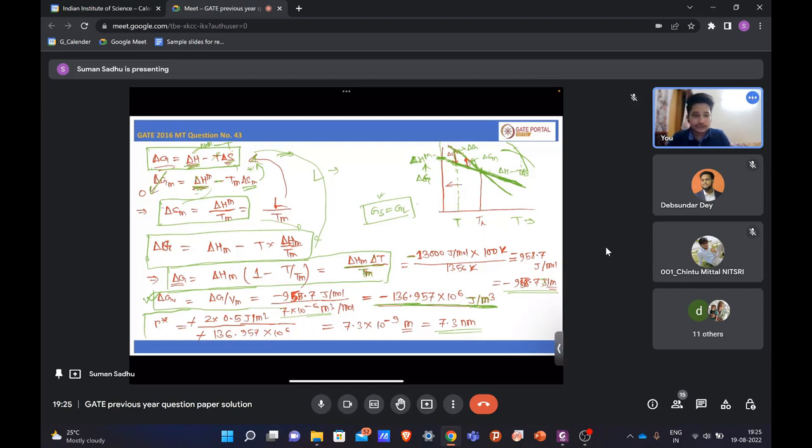But when a liquid is solidifying, what is happening first? A cluster is forming, right? That cluster is getting stabilized, so it will form a small nucleus of a solid, right? As soon as that nucleus is forming, it is creating a new interface between the liquid and the solid. Initially everything was liquid, so now you are getting an extra interface, the liquid-solid interface. In order to create that interface, you have to give some amount of energy, right?